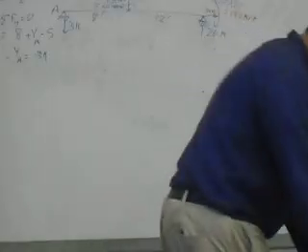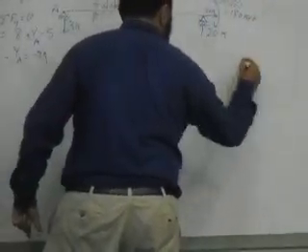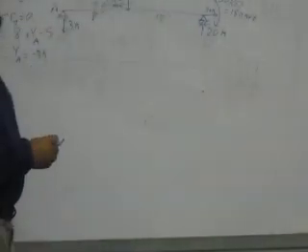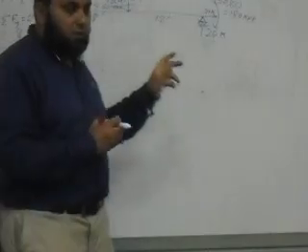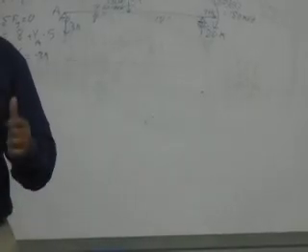So when I draw my shear force diagram, I draw it in a different shape. Again, you will not see the moments there; these concentrated moments will not translate in the shear force diagram at all, you only see the forces. However, they will have an effect.